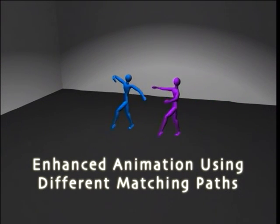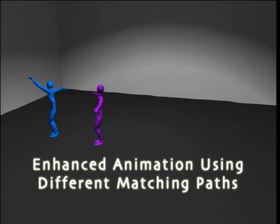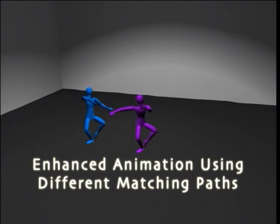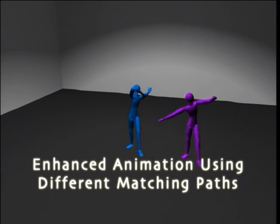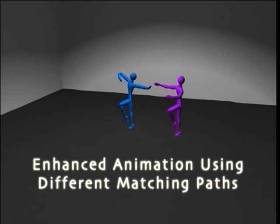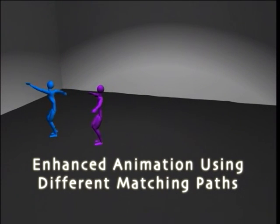For example, in this animation, the upper body motion of the blue character was synthesized using only the left hip and left knee X angles as the matching angles, while that of the purple character was synthesized based on all of the angles of the left and right hips and knees. Notice that the resulting animations are quite different, but in both cases the upper body is coordinated with the lower. Ultimately, the matching angles and paths are parameters that the animator can manipulate to achieve the final animation.